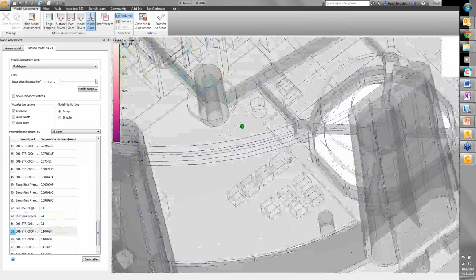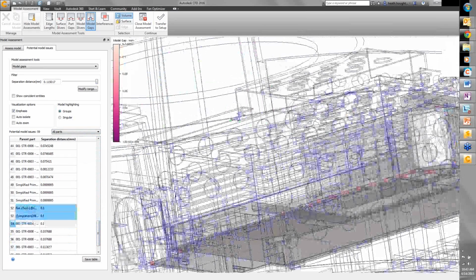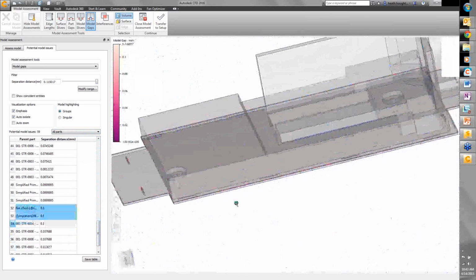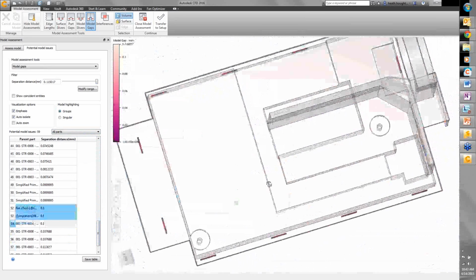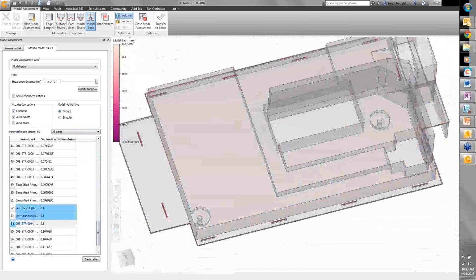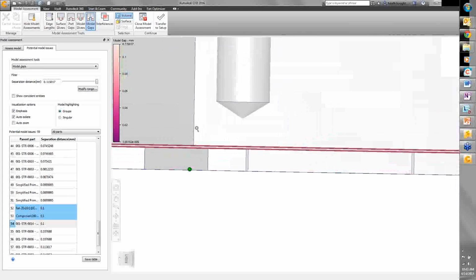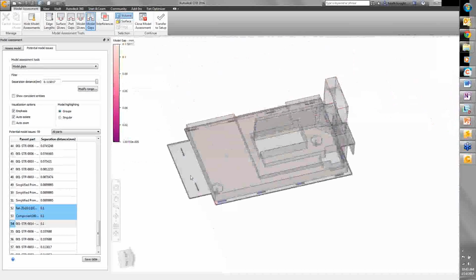So one of the things to point out as well is look at this one. Now, I thought this assembly was pretty large. I'm going to actually isolate it because this is a complex model. This whole region may not come over real well on the GoToWebinar, but you can see this whole region is a gap that's 0.1 millimeters. Not the greatest thing we want there. Now, this model actually meshes. I was surprised. Our mesher handled a 0.1 millimeter gap for a large region. But if I were to have a failed mesh, that would be the biggest red spot I could find on the model. That's what I'm going to go look at.